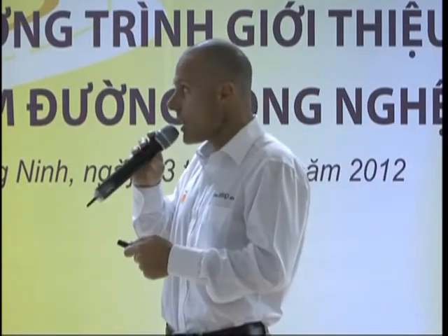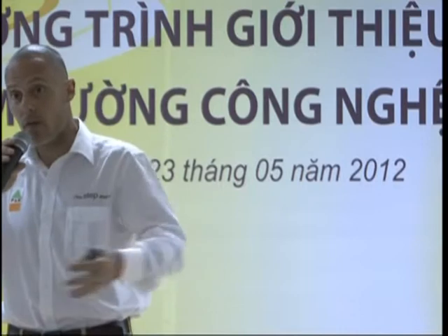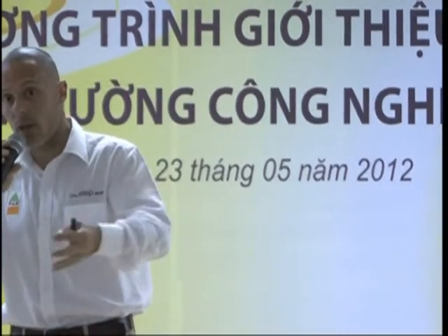Second point, by seeing what you have, you can select, because, for example, our machine can work efficiently with rocks up to 500 millimeter in diameter, half a meter rock size. So you have to see inside if the rocks are not too big, for example. But also, when you rip the road and you make the surface loose, it's quicker for our machine to go through. So you do more work in one day. You can produce more.